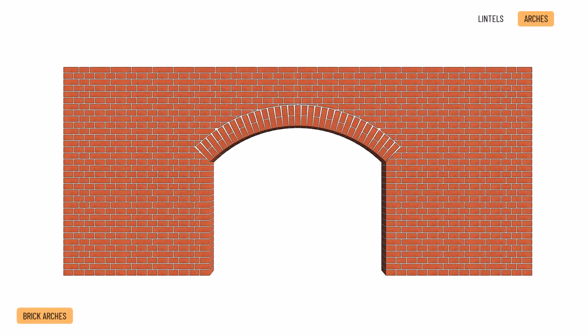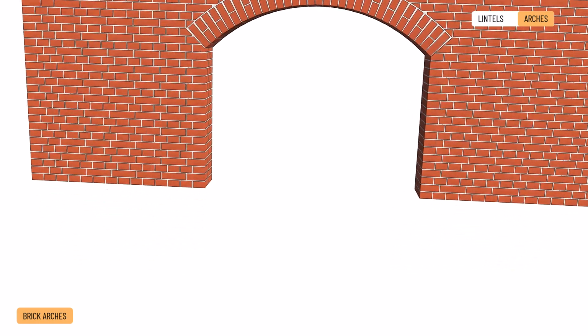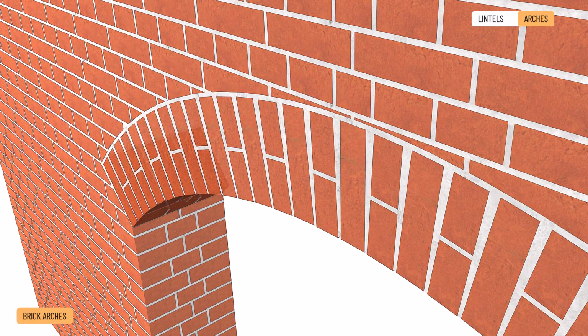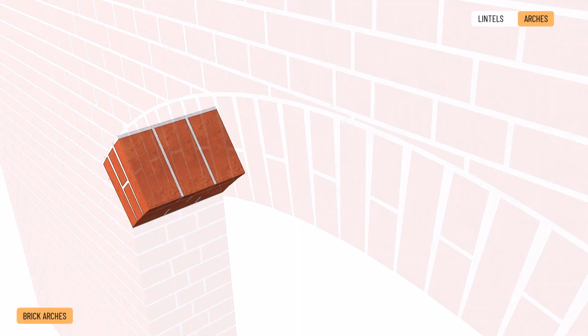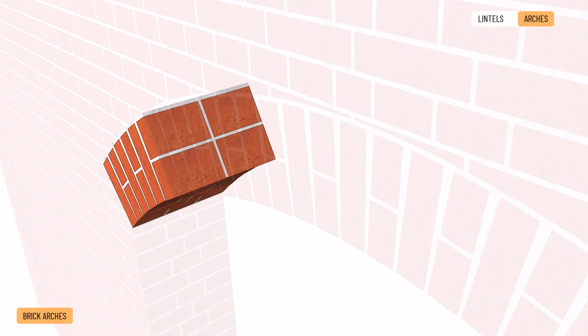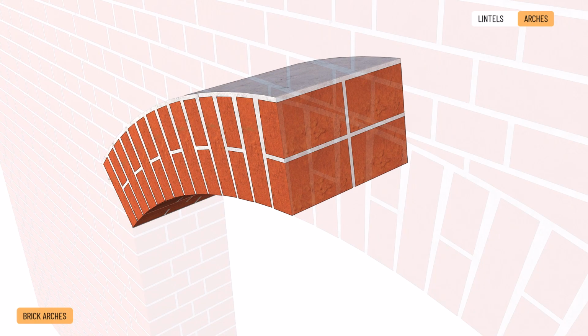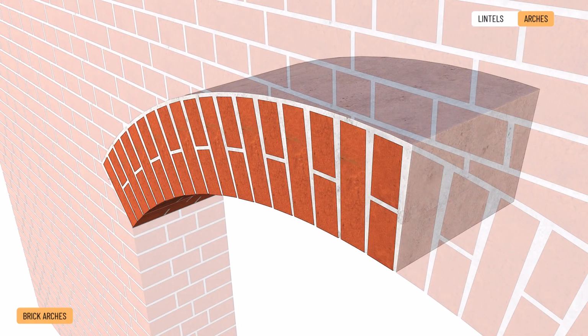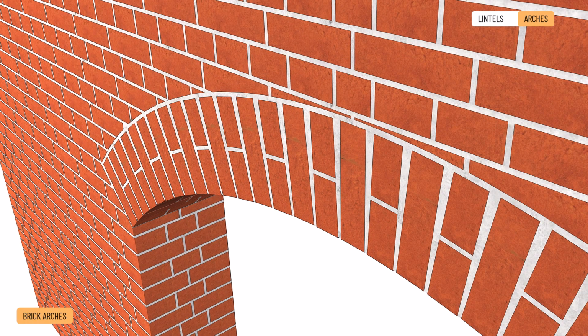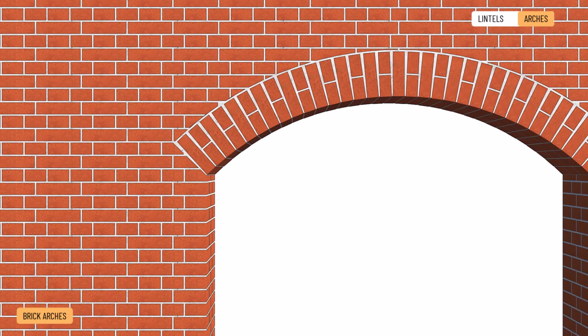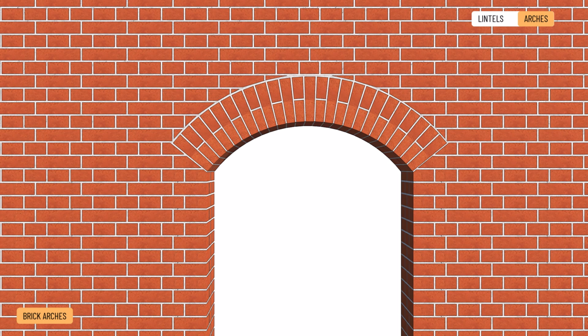Brick arches can be made in various shapes, using uniform or various reveal widths. The arches are built in a bonded manner, the same way as pillars. Typically, we use bricks without carving and with wedge-shaped mortar joints. However, large curvature arches with a small radius can only be masoned with wedge-shaped carved elements.